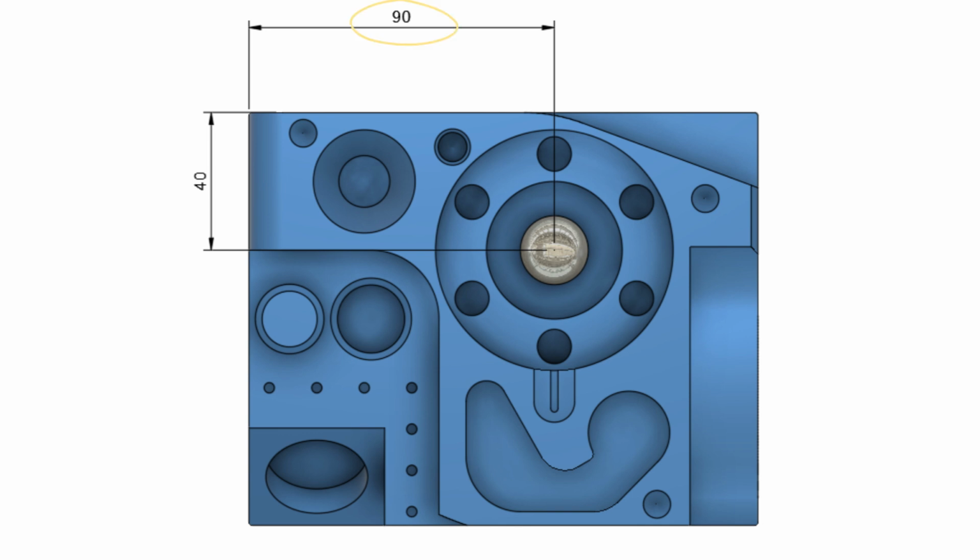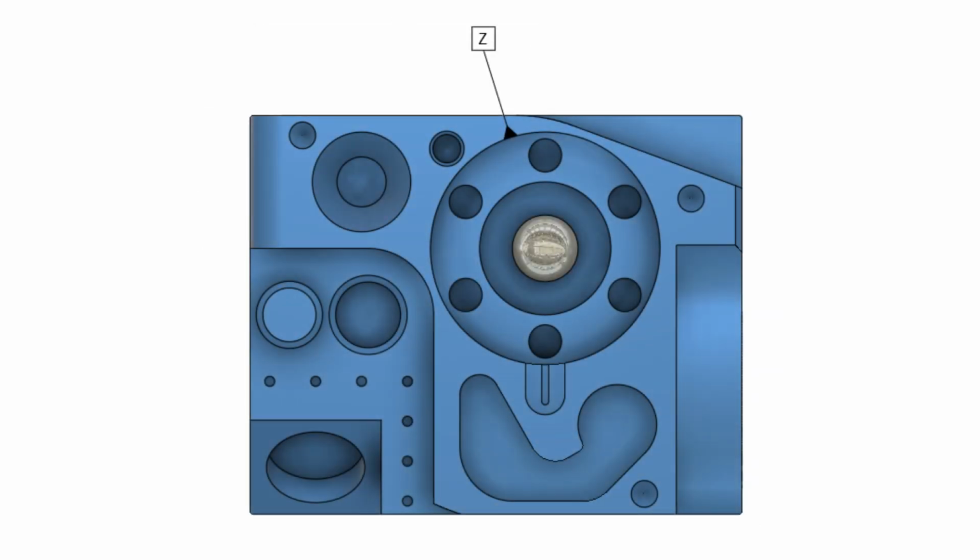This would be 90mm in X and 40mm in Y. Whilst this should work okay, it is prone to crashes. If the entire pocket shifts, the circular plane templates will stay as they are. This can easily be resolved by measuring the first bore of the pocket and applying it as a datum.